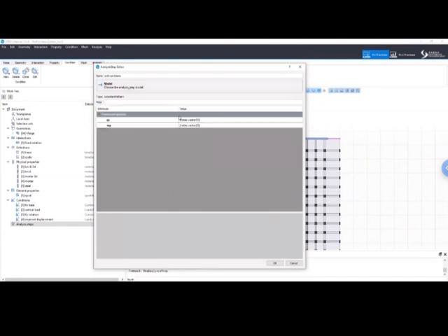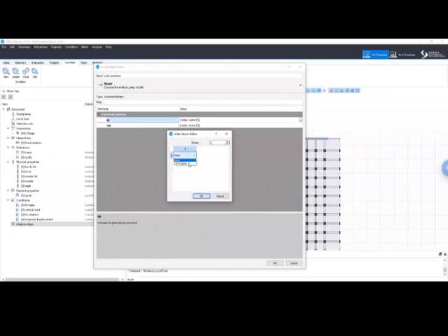So we click on this one, and here we can put all the single point constraints in this vector and all the multi-point constraints in this other vector. Now here we have just one single point, which is the fixed base, and one multi-point, which is the fixed rotation. So I go here, I make room for one, and I choose fixed base.